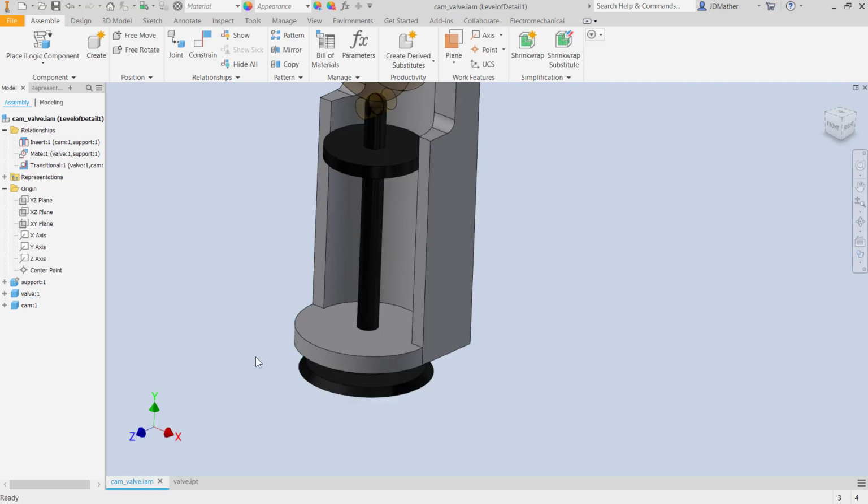We're talking about just a tiny film of oil. And then when you start up your car in the morning when it's cold, you'll get a big cloud of white smoke when that oil burns coming out your tailpipe. And it'll only last for a minute or a couple minutes, until it burns off all that oil that leaked past the valve stem. And so that's when you need to get a valve job to replace the valve seals, and they'll probably go ahead and do some work on the holes. They knurl the holes, actually, to displace the metal to make the holes smaller.